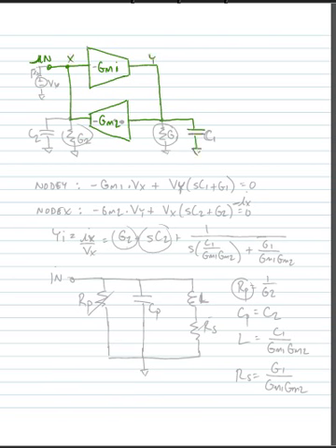Now, a real gyrator circuit has some capacitance due to the input of the gyrator. In other words, there would be some capacitance due to this GM1 on this node. So we'll call this capacitance C2, and it's the parasitic associated with the GM1. And we would also have an output resistance due to the GM2 device. So we can put an output resistance, or we'll label it as a conductance, in this case G2. GM1 would also have some output resistance, or conductance, that we'll call G1. And we'll label the capacitor at that node C1.